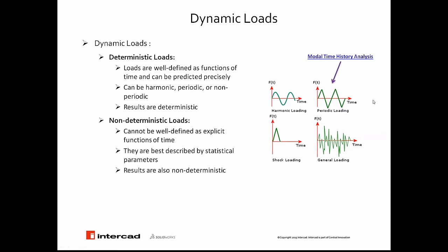For instance, if we have a periodic loading, then we are able to do a modal time history analysis. If we have harmonic loading, definitely we can do a harmonic analysis, linear dynamic. And if we have general loading with no prediction of the magnitudes and fluctuations, we can do random vibration analysis.